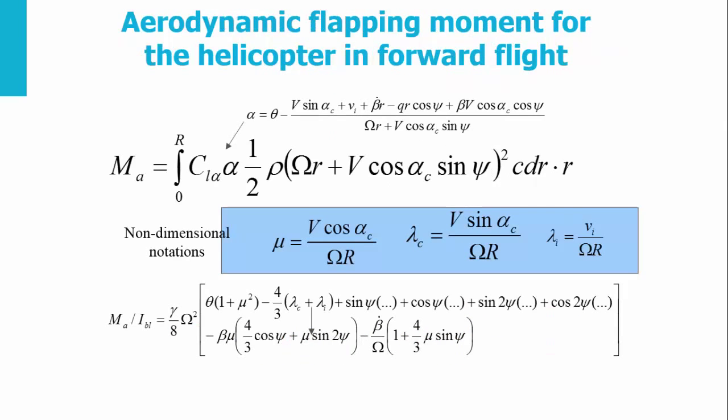Further, the aerodynamic moment can now be calculated as an integral along the whole blade from the lift force on every blade element. The angle of attack we have derived, and the tangential velocity on the blade is of course this component.